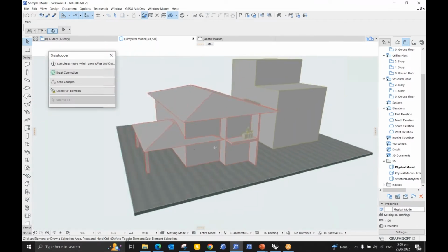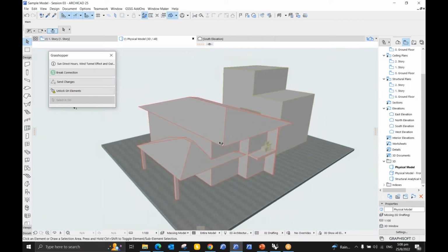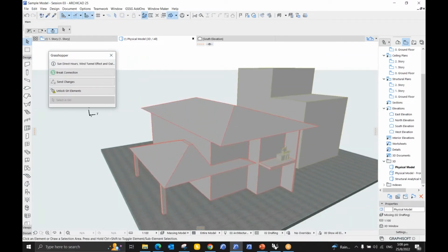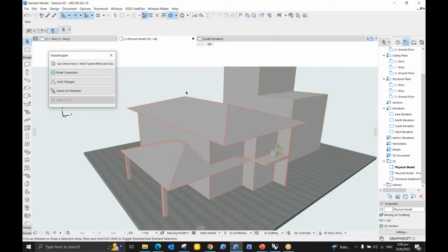And one tip that I would like to suggest here is to have the minimum number of polygons in your project. If you run the Grasshopper script for a large number of polygons, it will take a longer time to do the simulation, just like what happened to me last week. So I was not able to show the results of my simulation last week. I would suggest having a very simple massing model that represents more or less the building structure, and then do the modeling with that.